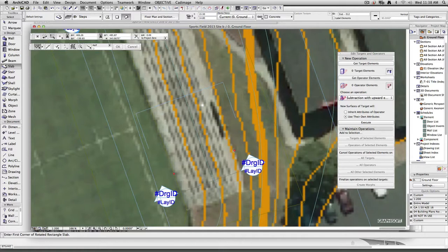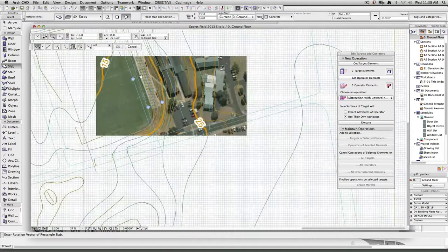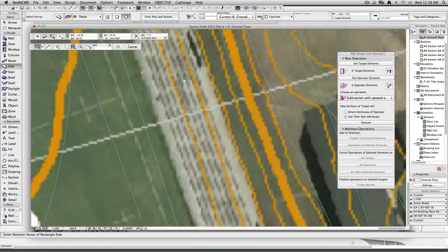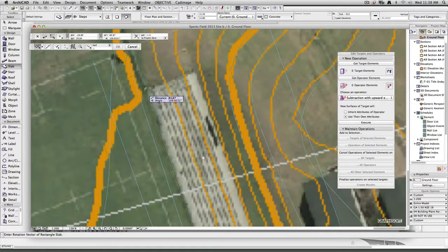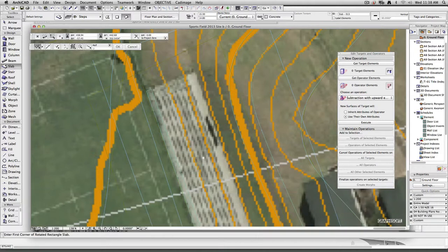I'm now going to draw my stair in here, so it looks like it starts about here. I'm doing a square and an angle here. I'm going to draw all the way back to here. Cool. It's looking pretty square. If that went off at a funny angle, I'd be a little bit alarmed, but it isn't. D1, so my step is 1. You want to type the number in because then you know exactly what you're dealing with, because later we're going to do a step and repeat and we want to know what the increments are.